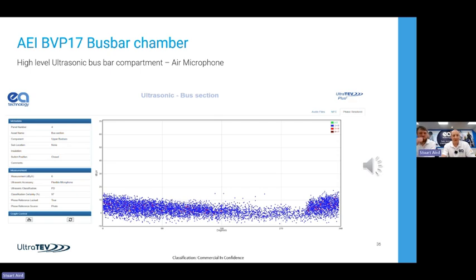And again, we can see clearly that the phase resolved plot is a bit round. You've got to imagine the phase plot goes right round the circle in this case, but you can see part of it on one side and the other side. We can quite clearly hear that it's definitely ultrasonic activity, but it's a very, very small gap. So it's not necessarily easy. We can get sound through very small gaps. So I can imagine inside it'd be much louder.